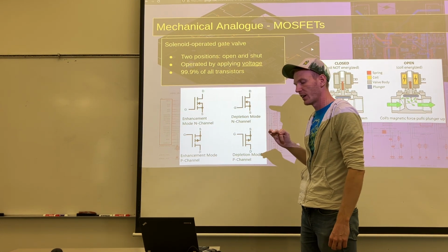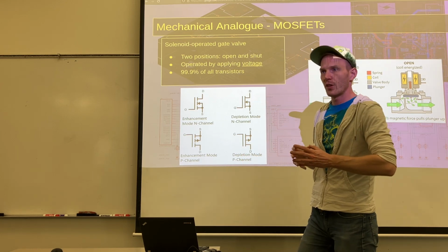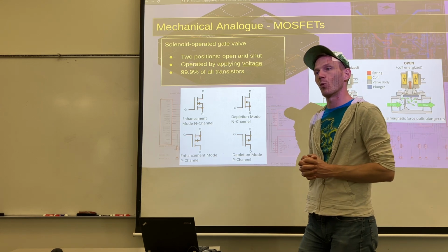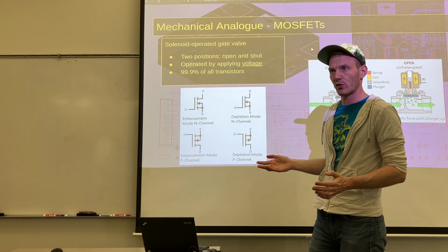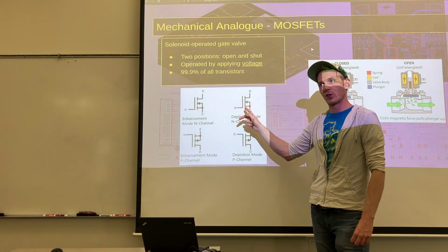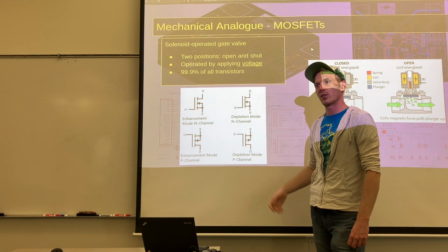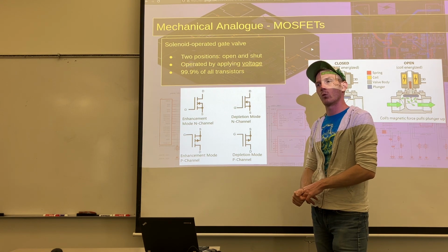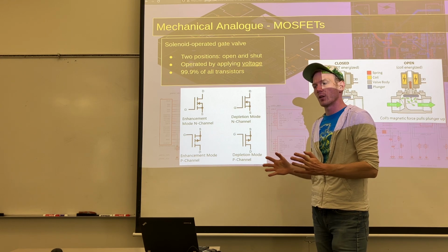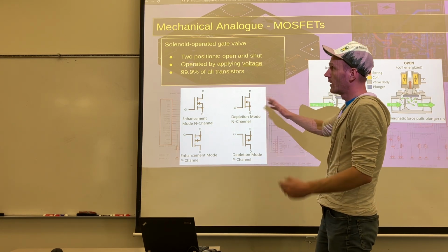This is kind of like a diode that will work, it depends on the transistor, but will usually work in both directions, but you get to tell it when to turn on and off. We'll look at some more stuff like that later, but this is a way of remotely controlling electron flow. That's what I want you to take away from MOSFETs.